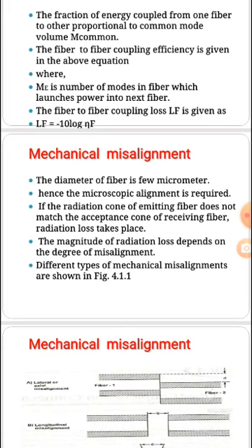So these things cause a huge amount of losses. And also splice connections. Of course, splice is a permanent connection. The loss due to a single splice is very less, but it is cumulative. It is added. There are so many splice connections from sending point to receiving point. So this we have to consider.